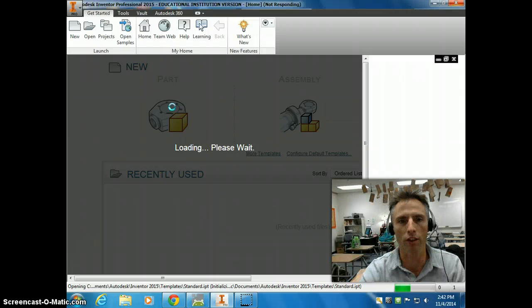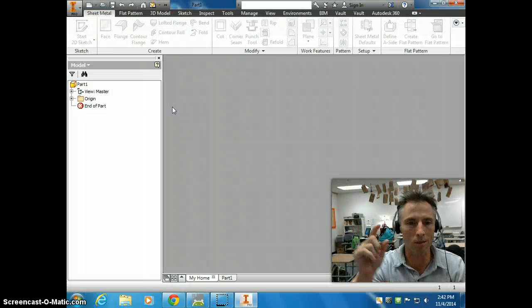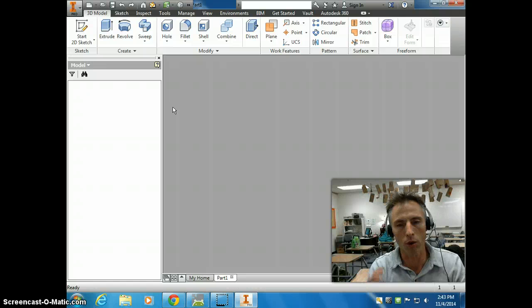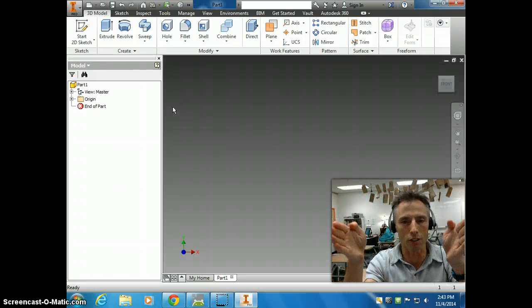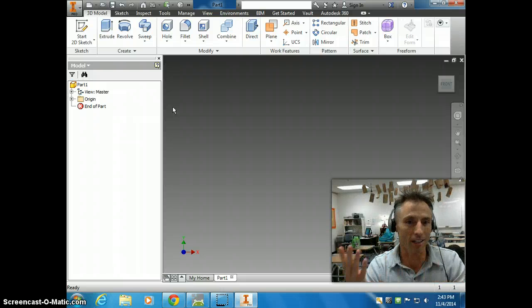Now, if you remember the chocolate mold project, you're going to probably mill a couple pieces of butterboard or wood or something. But we're going to assume that they have the dimensions of 2 inches by 3 inches. It's going to be a 2 inch by 3 inch block with a sufficient depth for whatever kind of mold we're doing. So we want to make sure that we're designing something that's going to fit into 2 of those blocks. So if the 2 blocks come together, our mold needs to fit inside there so that it's a cavity that's actually fillable.